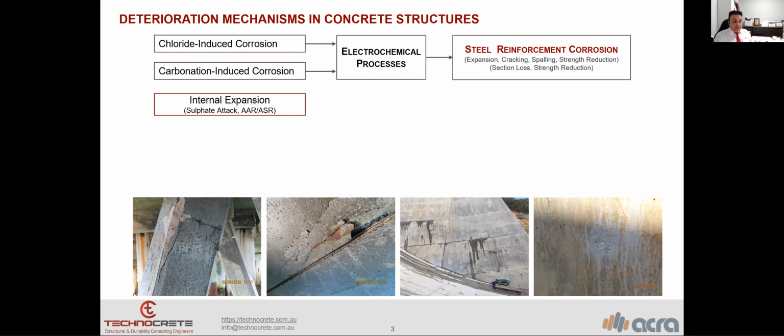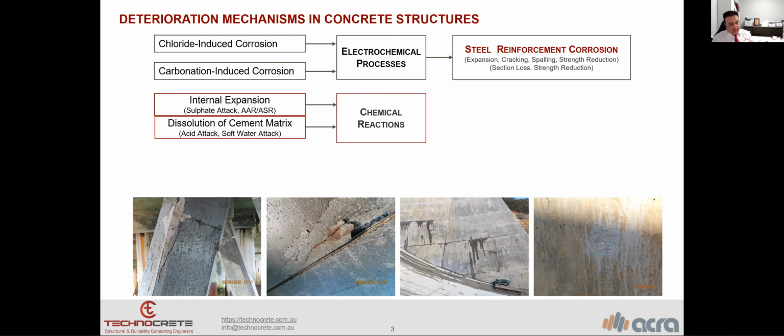We can have internal expansion, like sulfate attack and AAR or ASR. They cause the internal expansion of the concrete material. Or the solution of cement matrix, which we can see in the acid attack environment or soft water attack. Both of them are categorized as chemical reactions or chemical attacks.